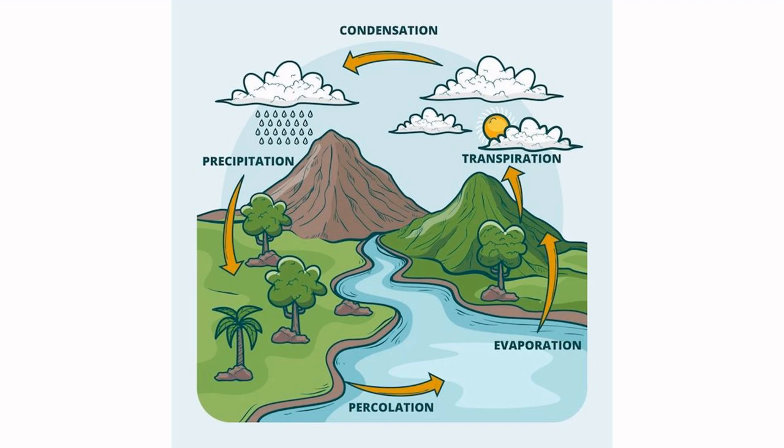This is a combination of the evaporation from open bodies of water, evaporation from the soil, and the transpiration from the plants. Precipitation is delivered to streams both on the land surfaces as overland flow to the tributary channels, and also by subsurface flow as interflow and base flow following the infiltration into the soil.